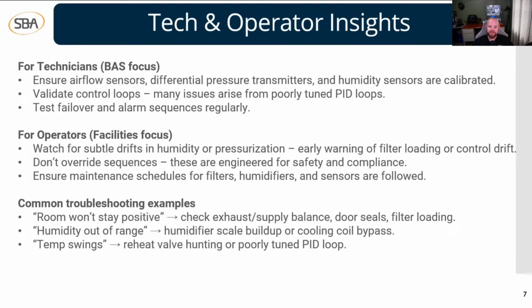The next thing I would check is door seals. These doors should have some seals on them, so when they shut, you're not getting any air infiltration through the door. Make sure that those door seals are good. If the seals have come off or if they've been broken or rubbed down over time, they may need to be replaced. Then the last one here is filter loading.